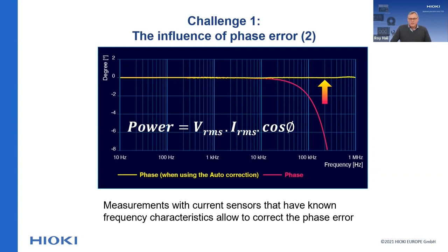All the different current measurement methods create phase errors. Internal shunt resistors, for instance, have a low resistance and are by nature inductive, which makes them unattractive for high-frequency measurements. EOP is predominantly using external current sensors with a voltage output. This type of current sensor will cause a phase error, as you can see in this frequency diagram.